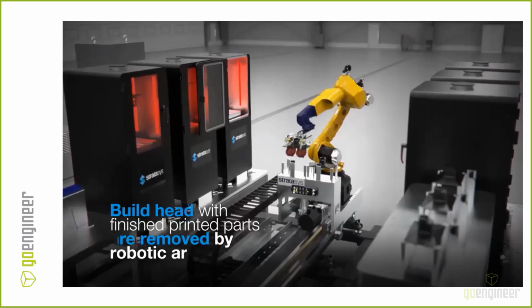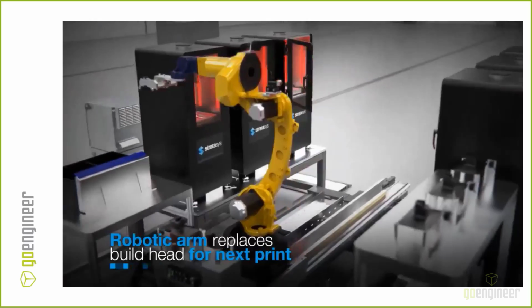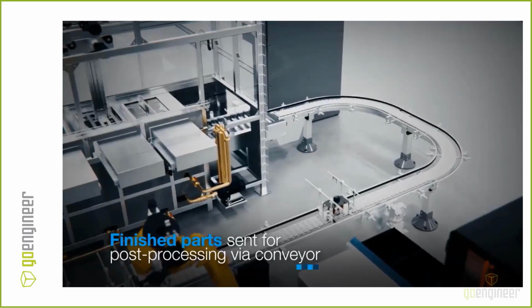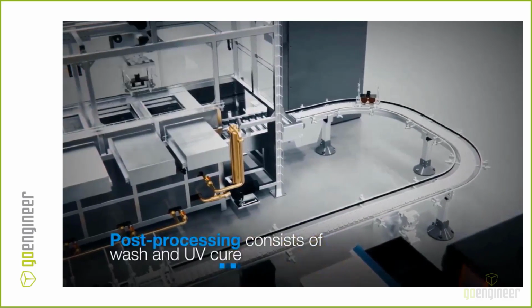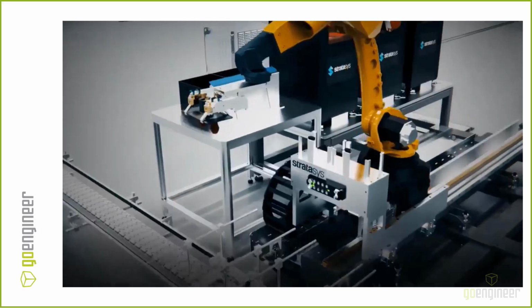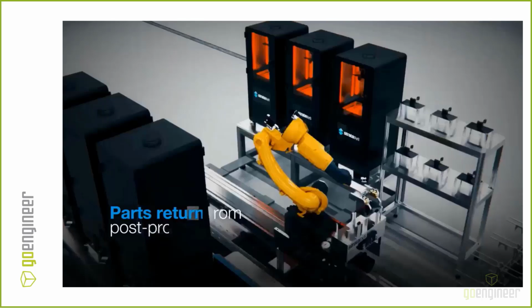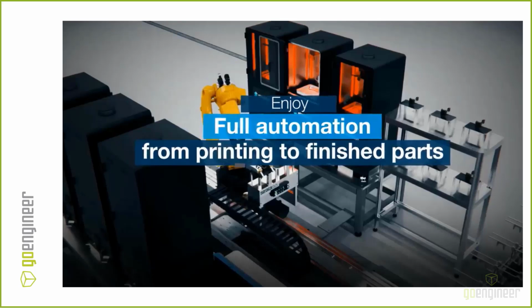And here's how it works. Parts are printed on the Origin 1 3D printer, and after printing, the robotic arm removes the build head with the attached parts. The build head is then taken automatically to the washing process. After part washing, the parts are UV cured. Finished parts are scraped from the build head and placed into a bin, and then the empty build head is automatically returned to the next available printer. This automated process ensures continuous production from printing to final part, streamlining costs in post-production while maximizing throughput. The P3 automated production cell can also be configured with any number of printers and various post-processing equipment options to suit different production floor volumes and needs.